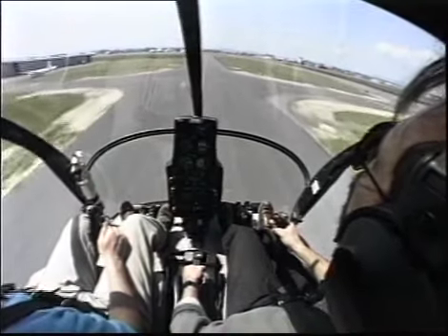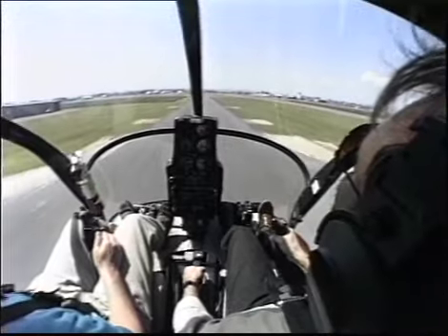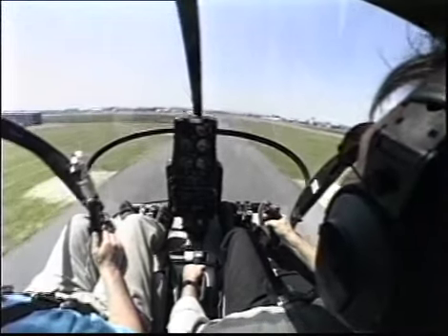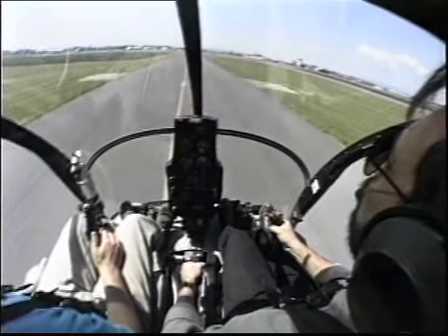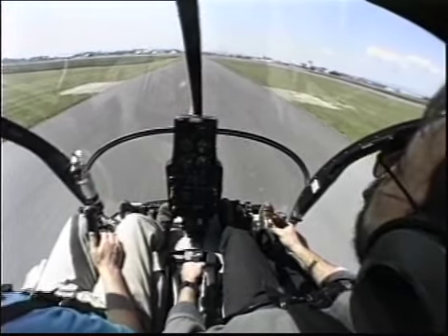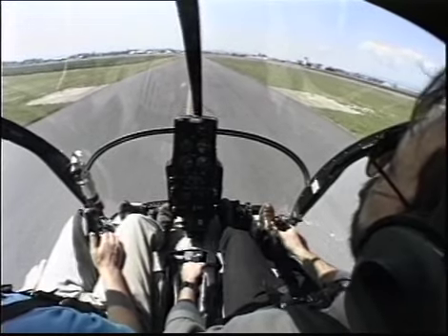Once the helicopter has slowed to the desired ground speed, apply forward cyclic to level the aircraft, increase collective pitch enough to prevent or slow the descent, and apply left pedal to maintain heading.